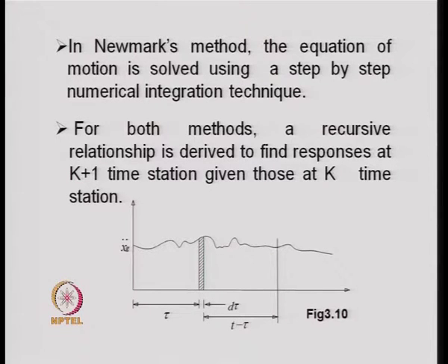Let us take the Duhamel integral first. As you know, in a Duhamel integral, we consider the load to be a series of impulses, that is the load consisting of a series of impulses like this.